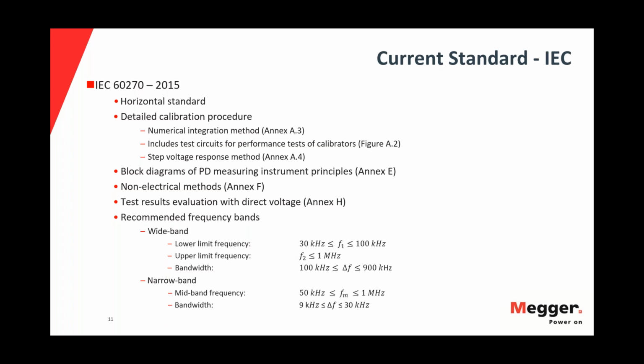For example, if you connect at the terminal of the transformer, measuring at 1 megahertz can cover the whole transformer and even a little bit of the cable connected to it. But if you increase the frequency, you will localize more and more to the area near the measurement. More will be explained later.